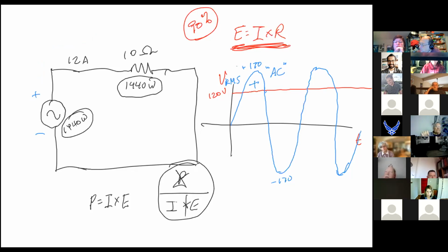Positive to minus. That's right. It flows this way out of the top of the battery. But now we're going to look at the other side down here. Can everyone see that yellow mark? Okay, when that is true, what happens to the battery voltage? It reverses, of course. And the current is no longer flowing that way, is it? Which way does the current flow? Still out of the positive, but we have a new positive. Is the positive at the top or the bottom of the battery? Bottom. So the current is now flowing this way.